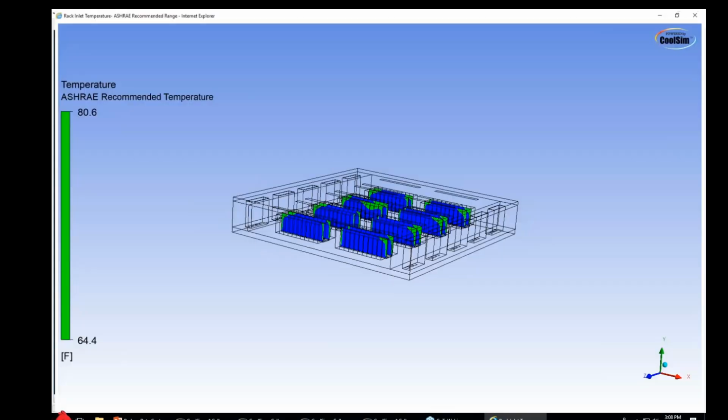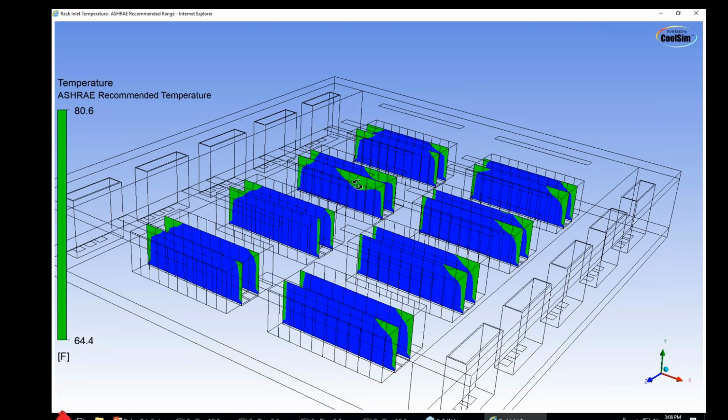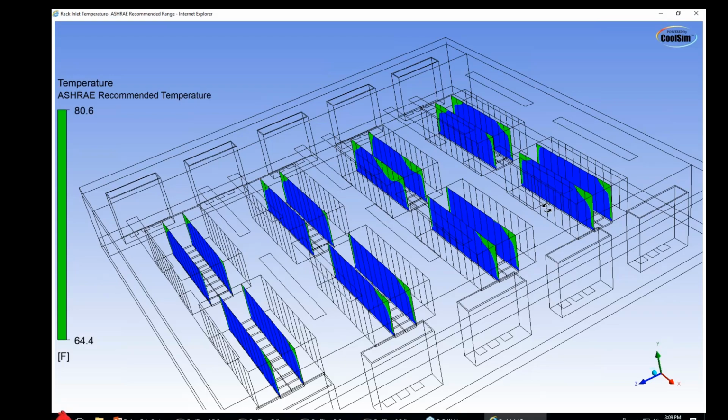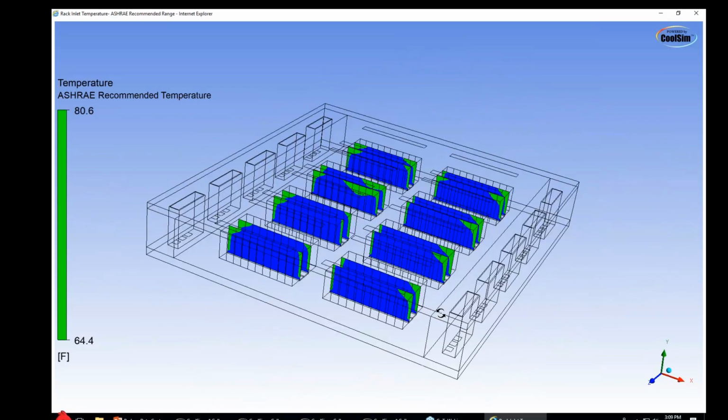And that's a very normal plot of temperature. Now this one, I was cutting down the RTI a little too hard, but you see where it turns up. It turns up on the edges. So putting your sensors up high on a design that's raised floor, where the cold air is coming from the floor, you can probably get away with fewer. Probably don't need them down low. So you might be able to get away with just 1 per rack along the top if I were to try to save money. That's what I would do.